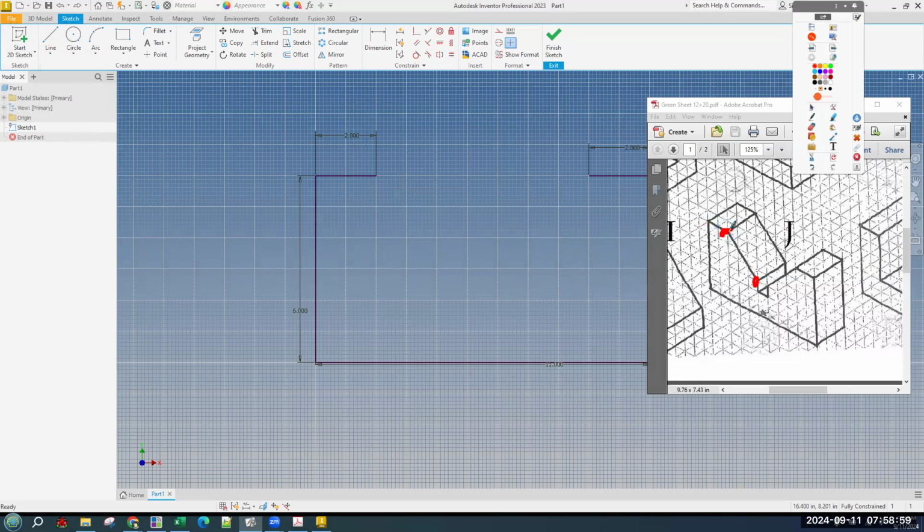If we can get a point here and get this point, acknowledge your sneeze, we can connect them, and we've got it. Okay, we've got this point, which is this point, but we need this point, which is somewhere down here. The way we're going to do this is by making this little trough shape here, just free floating in space, but that means we need to dimension it. And then once we have that, we can just connect.